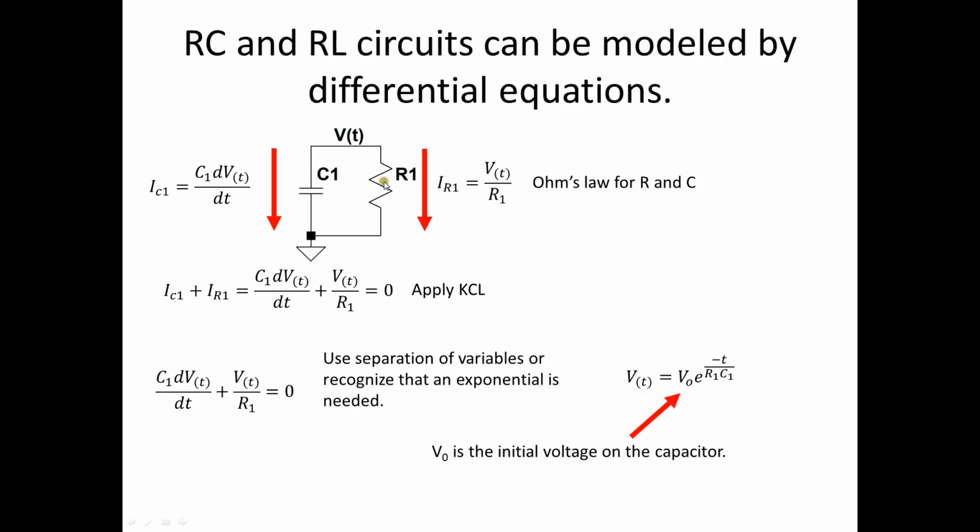And we have it drawn here, and we have the currents going through the capacitance defined by this relationship, and the current through the resistor defined by this relationship. We can use KCL to try to solve for the voltage and time, and we get the capacitor voltage plus the resistor voltage equals 0. Why is it positive and equal to 0? Because these are both going in the opposite direction, and I happen to be using the positive current direction with derivative direction definition of a capacitance current voltage relationship.